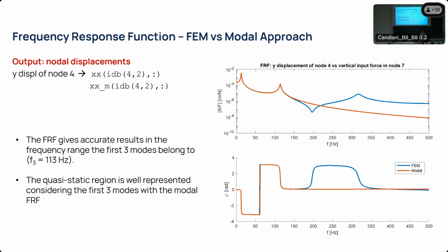If you're interested, there was an assignment a couple of years ago where a certain number of mode shapes was required, and even by adding more mode shapes, the response of the structure was changing. After adding the 6th or the 7th one, it was changing completely, because some mode shapes have an influence in some areas of the structure, and some mode shapes do not have an influence in other parts of the structure. So it's up to your sensitivity to play a little bit with the parameters of the reconstruction and see what happens. Okay.